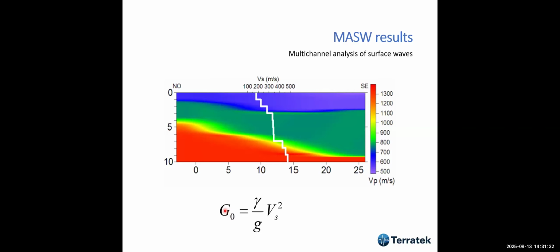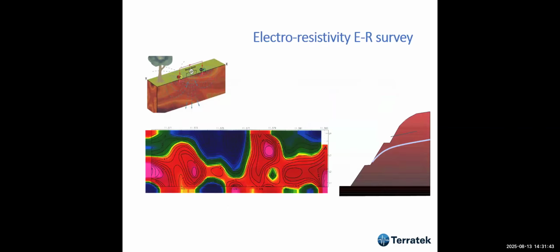And this shear modulus today is a must in most cases that we do numerical analysis, we do numerical modeling. This is very important. The other thing that's very important to have in many situations is to carry out electroresistivity. These can locate the rock, locate the water table. And I always have a geophysicist helping me to analyze these data because I'm not a geophysicist, as I've told